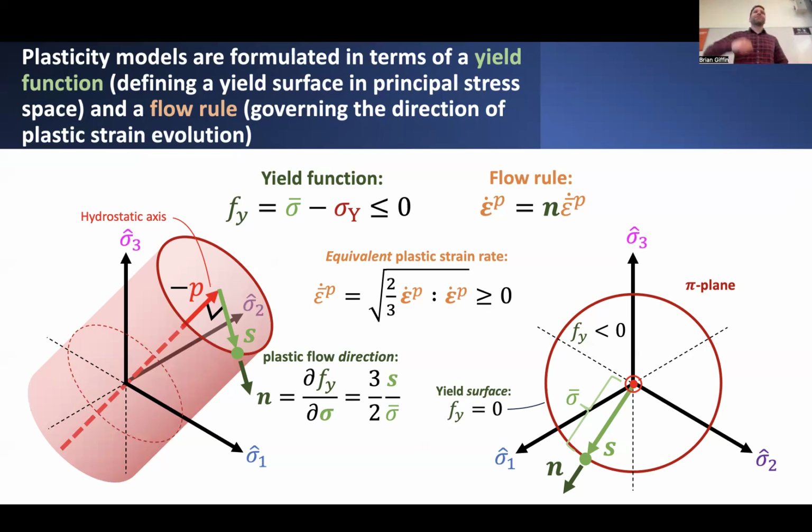And we can't just change it willy-nilly. We can't randomly decide, well, let's update the plastic strain, but maybe increase it in some arbitrary direction of loading that may or may not be aligned with the actual applied loading to the structure or chunk of material that we're looking at. We actually had to insist that the direction in which the plastic strain changed or increased had to be directly proportional to the state of deviatoric stress in the material.